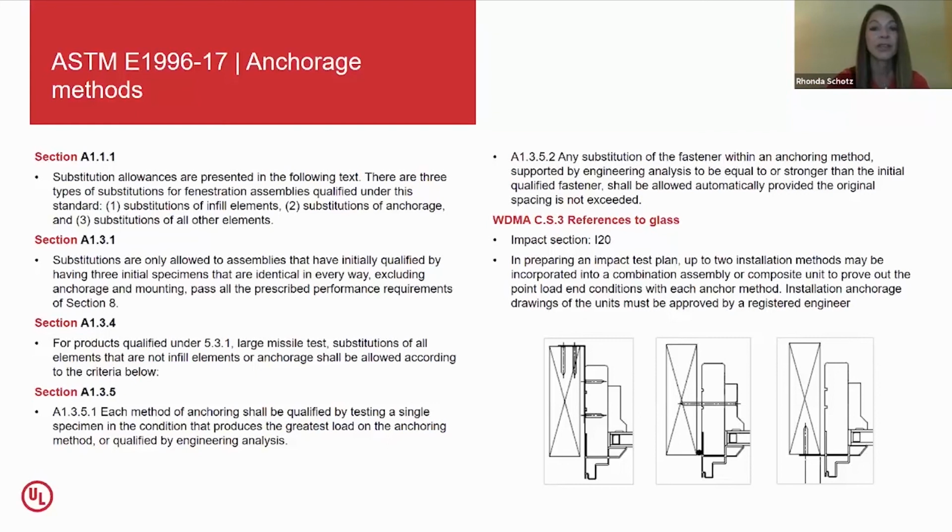The older versions of ASTM E1996-14, section A1.3.9.3, did not allow multiple anchorage methods on the 3 identical specimens in the past. The image in the lower right corner shows installation masonry clip method, screw-through frame method, and nail fin installation method.